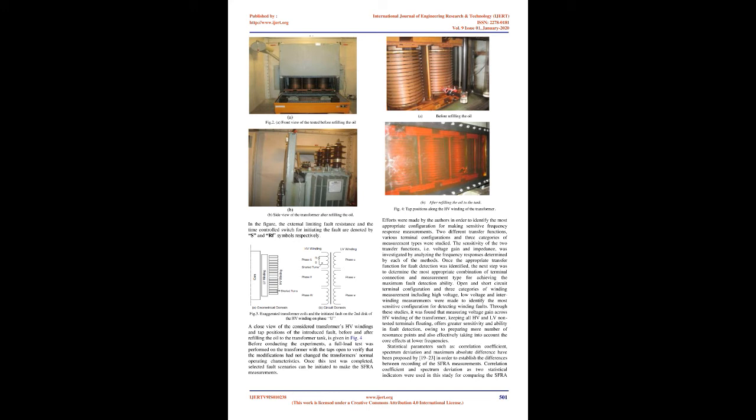The next step was extracting leads from the tapping points on the chosen conductors. Low-impedance insulated wires were attached to the conductors by means of specific clamps embracing the conductors at the tapping points. The leads were then brought out of the transformer to allow easy access to the internal turns and also provide the possibility of externally producing inter-turn faults. Since it was difficult to quantify exactly what number of turns was involved by the fault, after the connections were completed, the winding was energized by a low-voltage power supply and the open circuit voltage between the tap conductors was recorded.